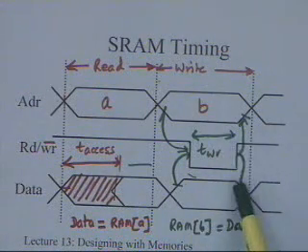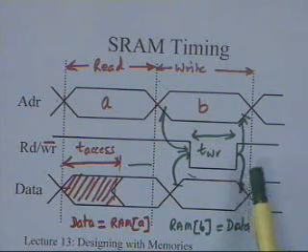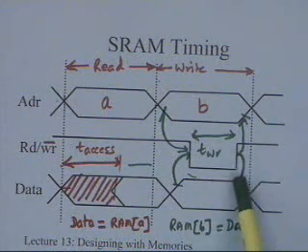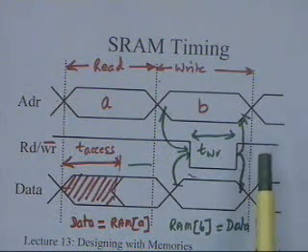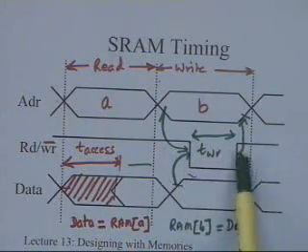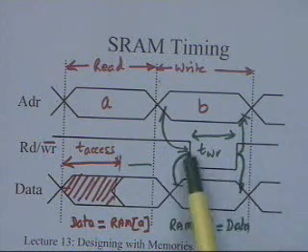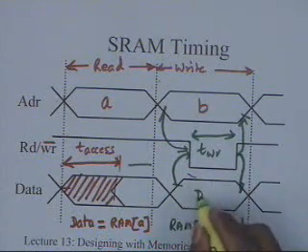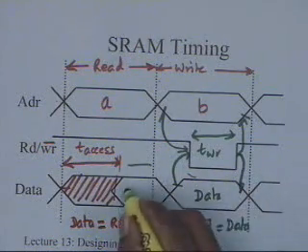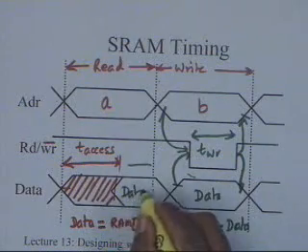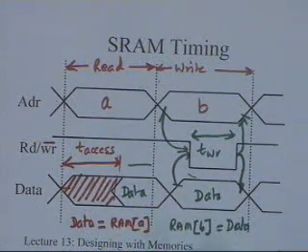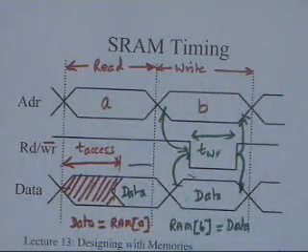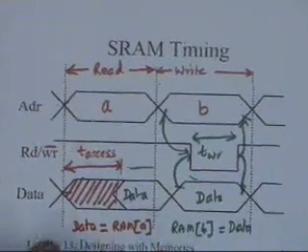Hold time, how much hold time is there? Sometimes some devices are generated with zero hold time, which means that these can actually occur together, but they should never occur later. That's what a zero hold time means. But you may have a requirement of a small hold time and a setup time over here, and you have to ensure that. So this is your data, and this is also your data. So this is how the timing looks in case of a RAM device.